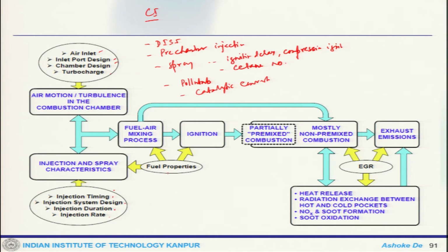So, these will actually determine the spray characteristics, because this will tell you what kind of spray you are going to have, and that has a direct impact on the combustion characteristics inside the cylinder. When that happens, basically that goes to the mixing process. Obviously, mixing is indirectly also impacted by some of the fuel properties.